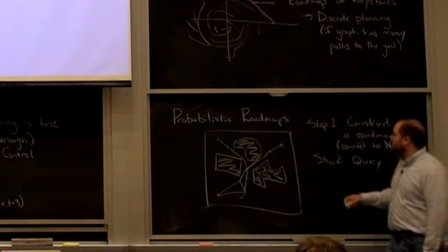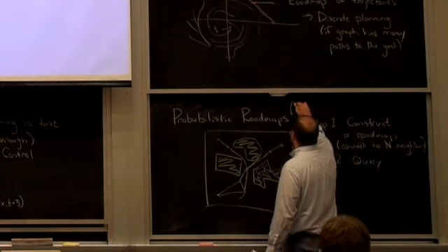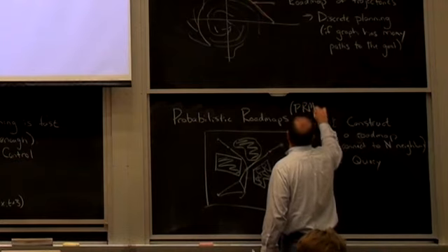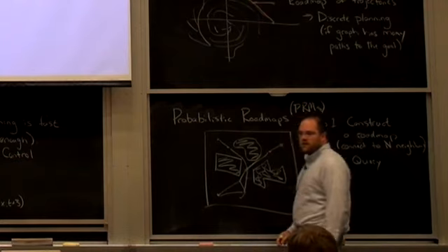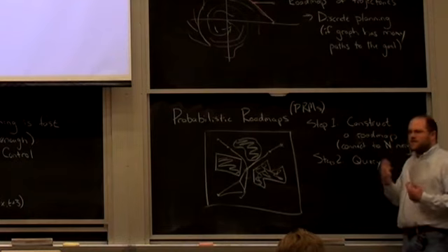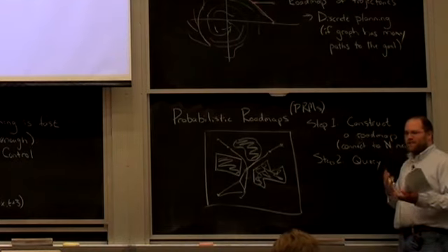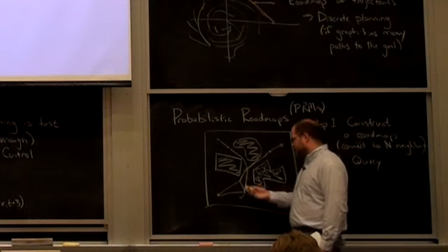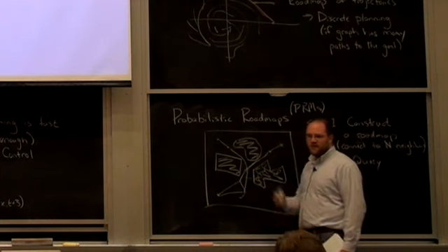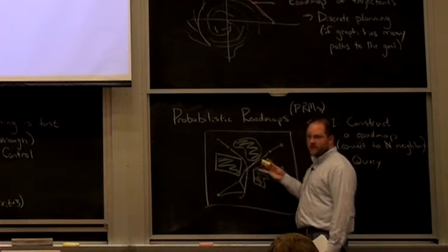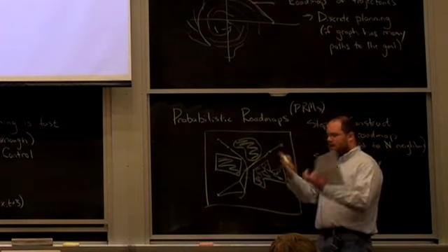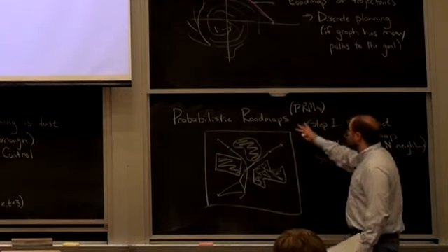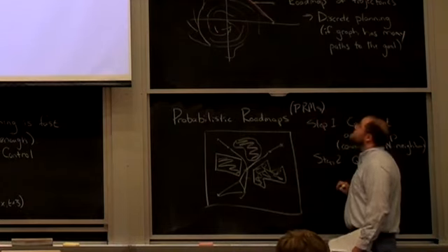Right? These are the other ones. The rapidly exploring randomized trees goes by RRTs. These go by PRMs, probabilistic roadmaps. A lot of people seem to think that they're intellectual competitors with RRTs, and I don't think that they are really. I think the RRT guys would just say that, well, you just use an RRT to make the connections, and the roadmap is still a very good idea. And I think RRTs sort of effectively make roadmaps. So I think they're very harmonious ideas.